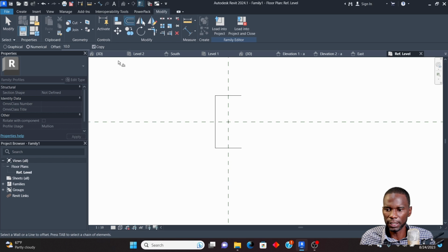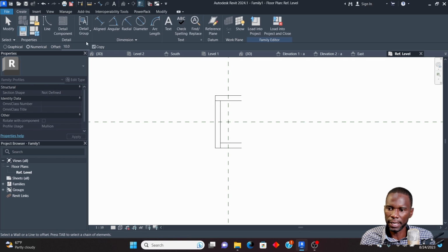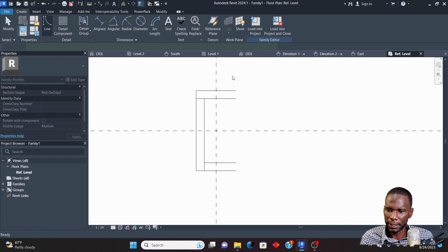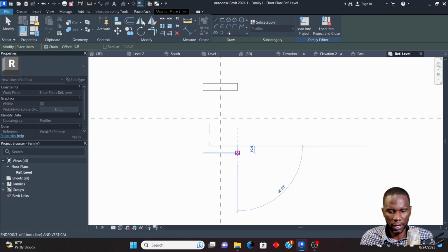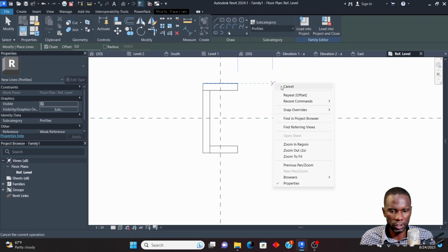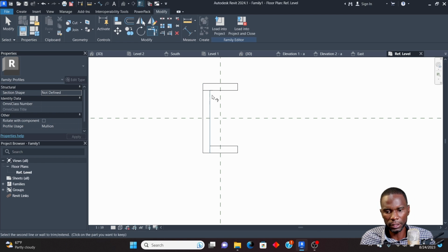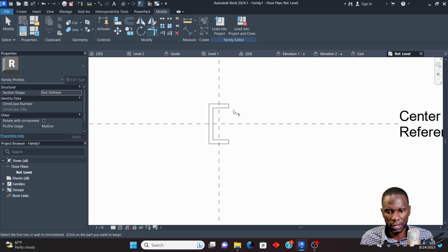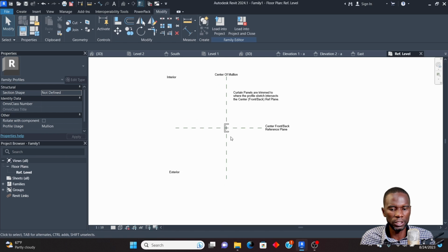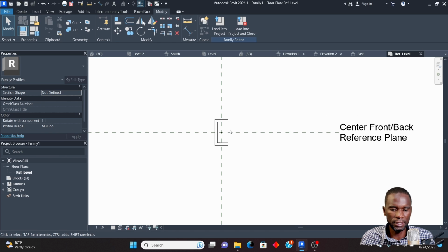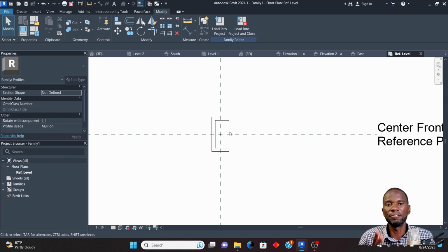I'll go to offset. Then 10 is actually right there, so I can do that to make sure that I have 10. Then I'll go to create, pick line, and pick line once again, and make sure that you close it like that. This is my channel. You can be specific with any channel that you want to create. TR on my keyboard to trim, and that is my channel. It's complete. As you can see, you can add fillets and anything according to how you want your channel to be. This is the mullion that you want to have, because we don't have it by default, so you need to create it.